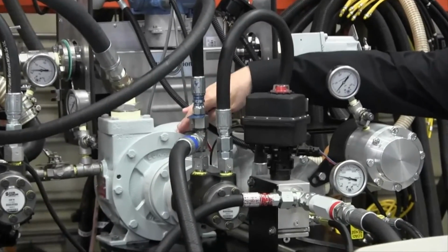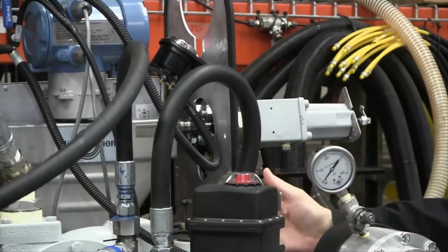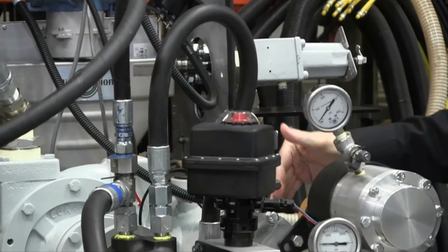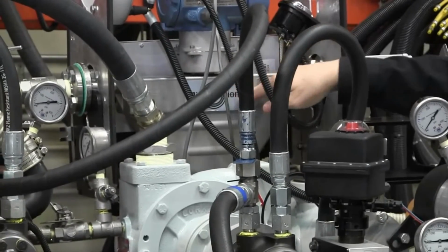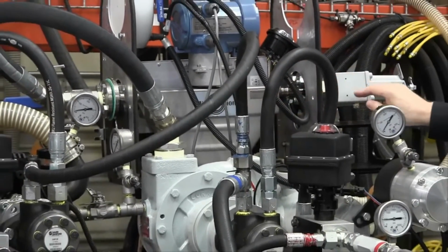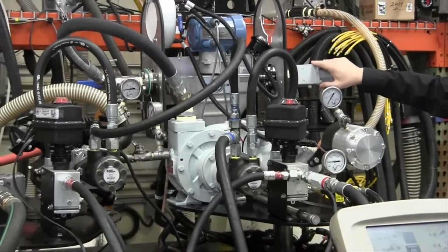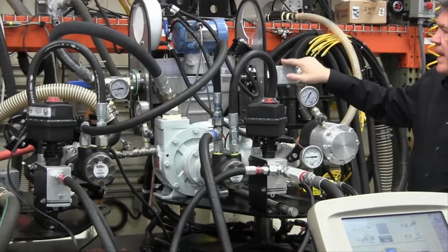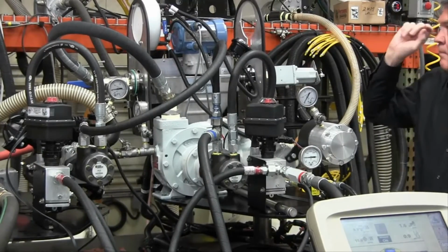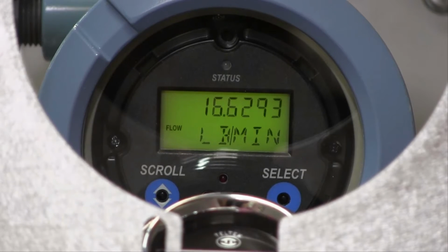The sliding vane pump is here. On a flow basis it's coming in through the phase shifter, into the sliding vane, around and out the sliding vane, into the mass meter, out past the mass meter, past the discharge valve, and we'll explain the discharge valve a little later. The mass meter is reading the flow, and right now it's reading a flow of about 16 pounds per minute.